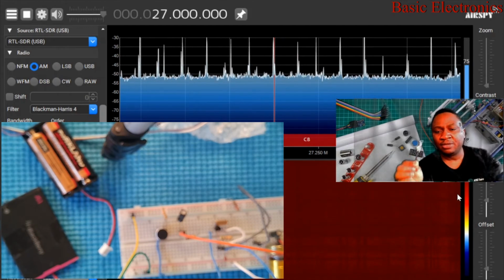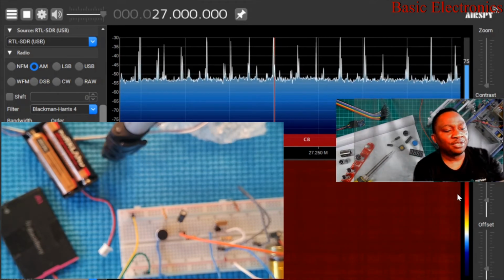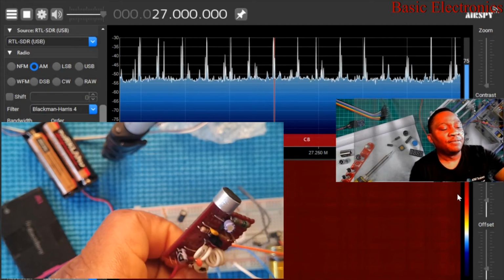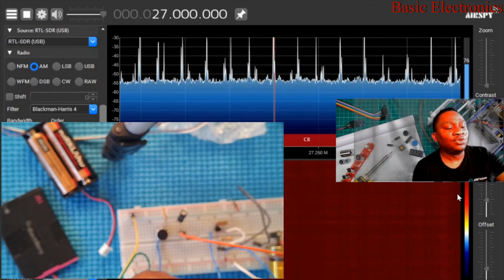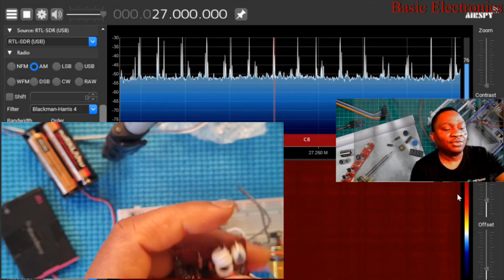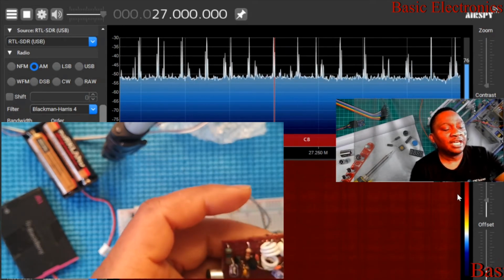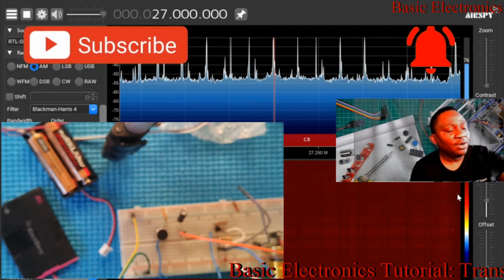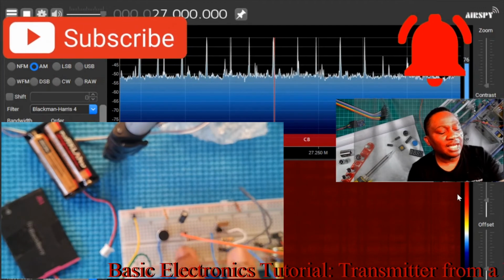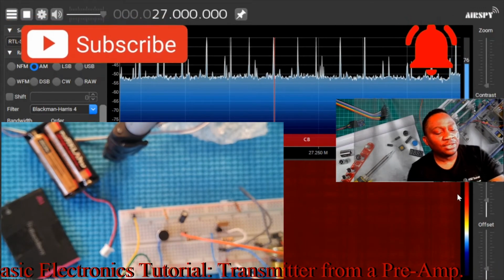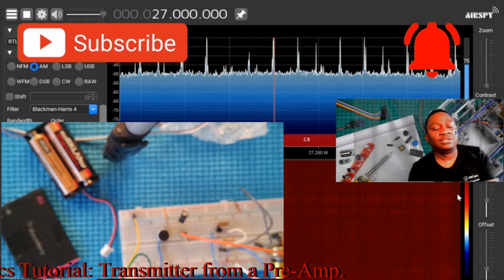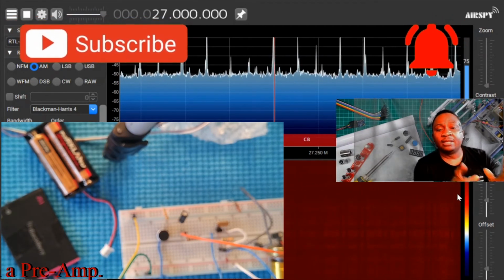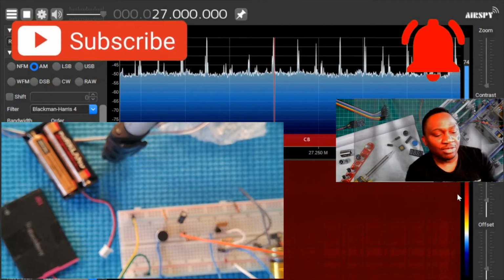And I have given you a way to overcome this. The problem with this voltage controlled oscillator is to use a voltage regulator and a slightly higher voltage than the threshold voltage of the voltage regulator, so that you can keep the transmitter frequency fairly stable over a longer period. But the one we have today doesn't require a voltage regulator. Just use your crystal. Try different crystals. Use a higher frequency crystal. And again, this is a very short range, low power transmitter.